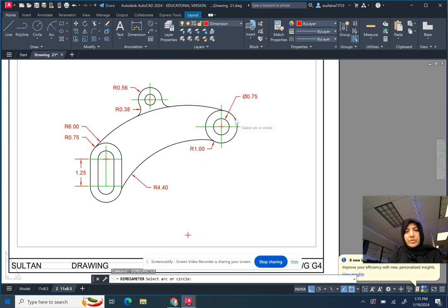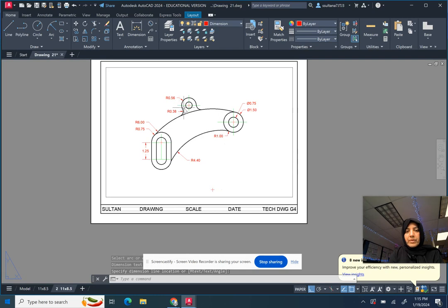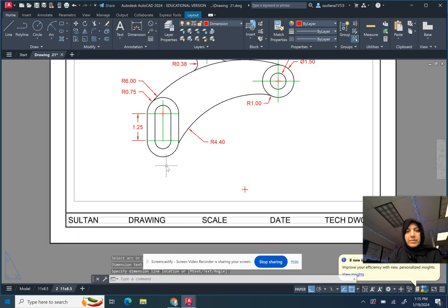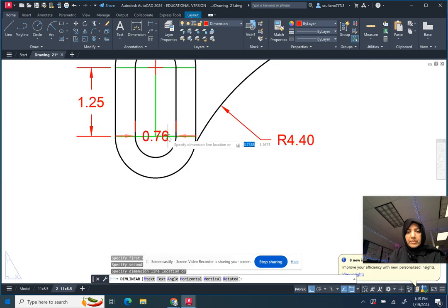Try to group all the dimensions whenever possible and stack them vertically. And diameter for this smaller circle. And over here, rather than diameter or radius for this, the given dimension was a linear dimension, and that's how you knew that that was the diameter.